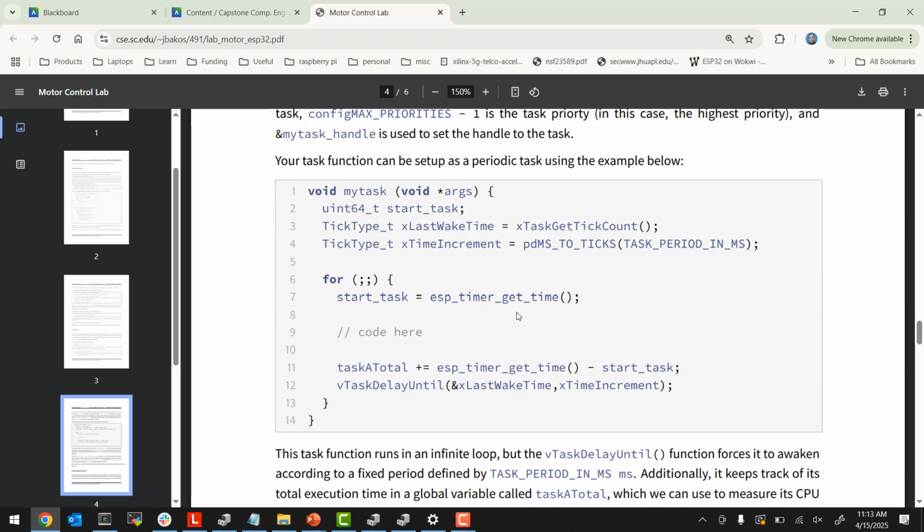This will guarantee a 0 jitter period. So even if for whatever reason this task gets delayed, the next time it fires will be exactly whatever the period is from the last time that task became ready. It makes sense when its period started. And then you could just insert your code here, and then you got it.